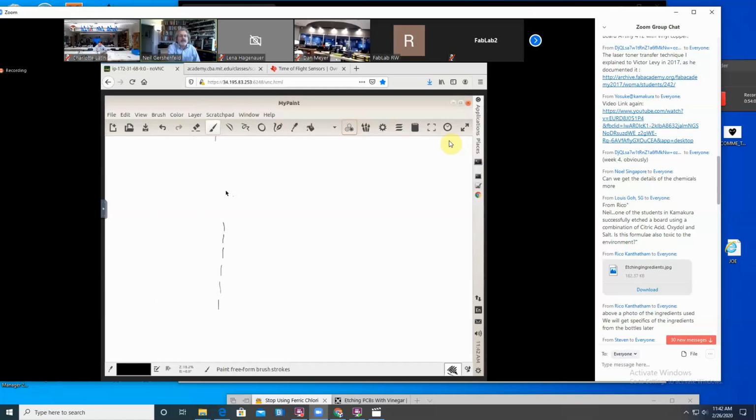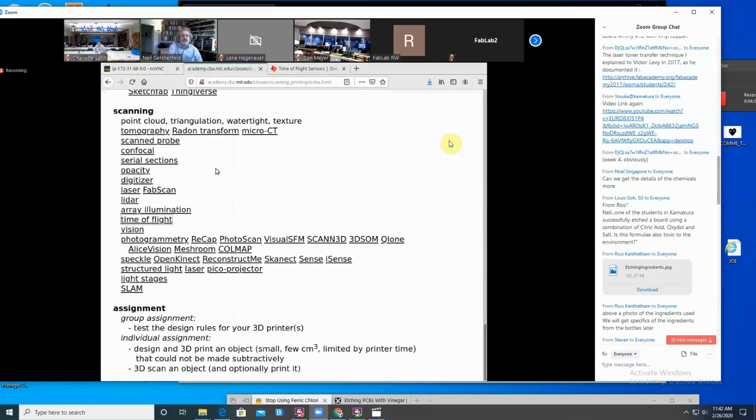The light you send out, light is a wave, but you put a wave on the wave, a modulation. It bounces off of the object and the light comes back in. Each pixel, in addition to measuring the intensity of the light, also measures the modulation. It measures the phase of the light, and by measuring the phase of the light, it lets you measure distance. So it's a camera that sees distance as well as intensity.